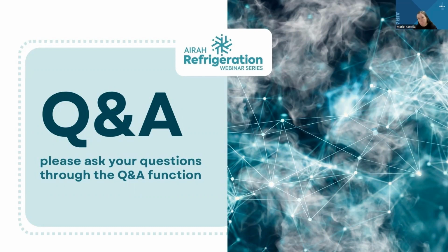Now, obviously, when you have people, especially in a production area, which is our refrigerated space, under the ventilation standard you need to introduce outside air. So you have to take into account the latent component of the outside air being introduced into the room. So obviously you will have a larger latent load component on your evaporator. I hope I answered that question.